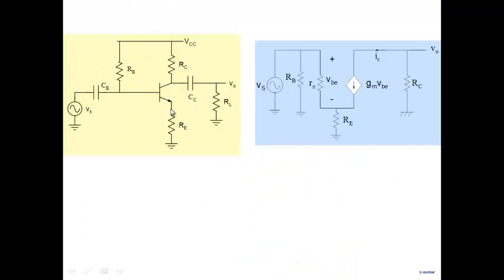Well, this circuit comes in very handy. Why? If you have a 20 millivolt signal, see our small signal analysis that we did, we can calculate the relationship between Vs and VBE. Note that what causes distortion, at least most people understand it that way, is VBE, the voltage that appears across the base emitter junction here. So the idea is, if you have 20 millivolt, if you can keep VBE to 10 millivolt, right? Are you seeing that this is an attenuator in some sense?